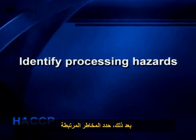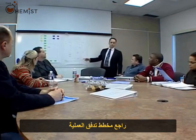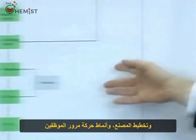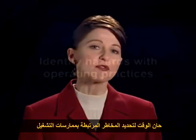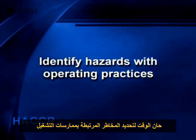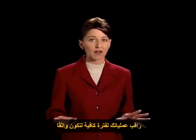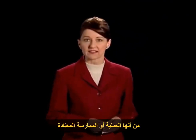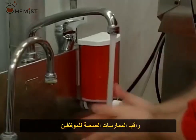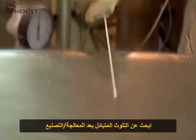Next, identify hazards associated with each of the processing steps. Review your process flow diagram, plant schematic, and employee traffic patterns. After identifying ingredient and process hazards, it's time to identify hazards associated with operating practices. Observe your operations long enough to be confident they are the usual process or practice. Observe the hygienic practices of employees. Look for cross-contamination after processing.